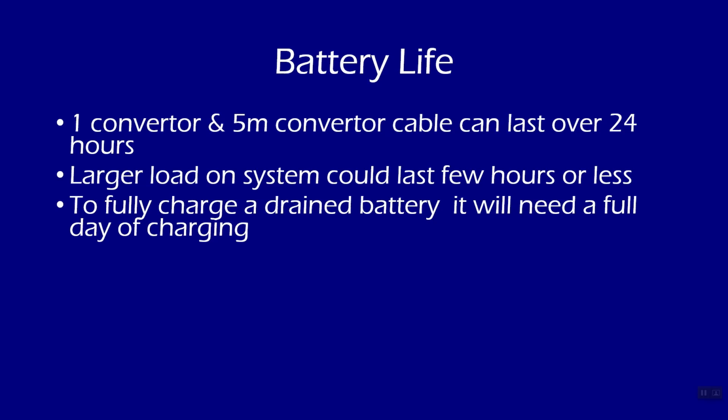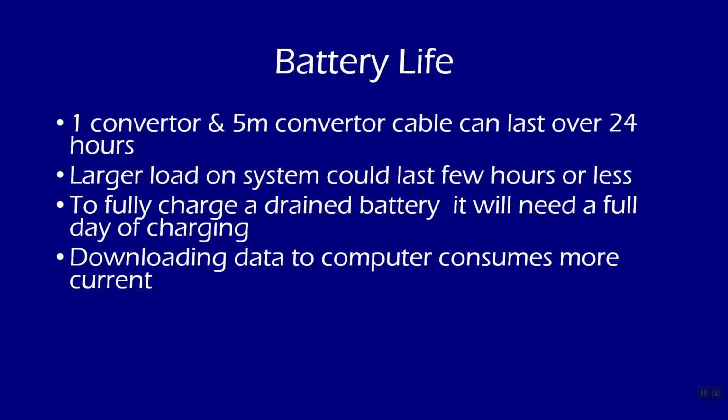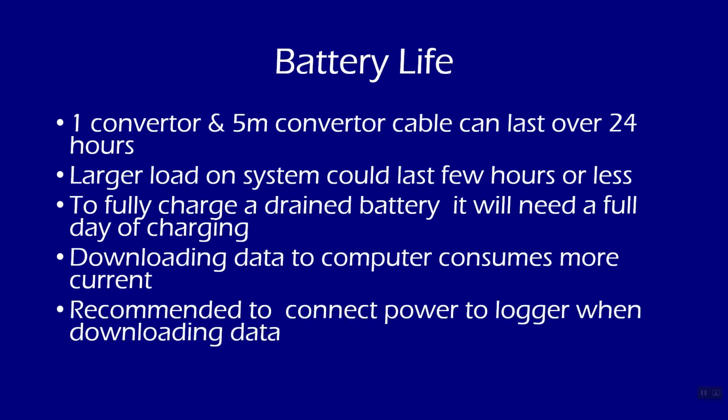An important point to note is that when you connect the logger to the PC to download the data, the downloading process could consume a bit more current. So say for example you had a logger in a remote location and you took it to the PC to download the data without the power supply. If the battery was low for whatever reason, a situation may arise where the downloading process drains the battery before the data is downloaded. So it's always recommended to connect the power supply to the logger when downloading the data.